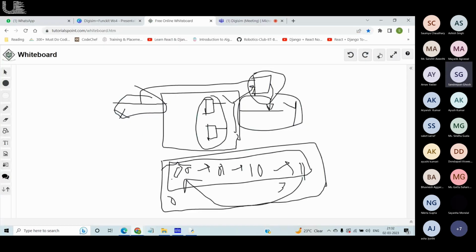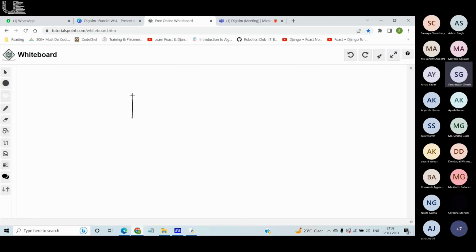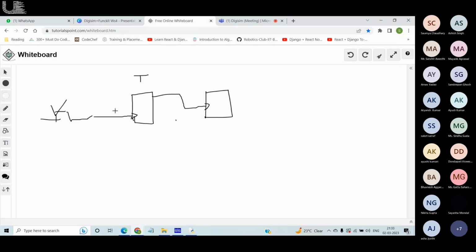So let me take two flip flops to show you what happens. Let them be T flip flops. So this is my count, using what it triggered on the circuit, what it should keep track of. Say I have a push button here. If I click this button, my count should increase by one. The output of this is connected to the clock of this. Initially, let the outputs of both the flip flops be zero.